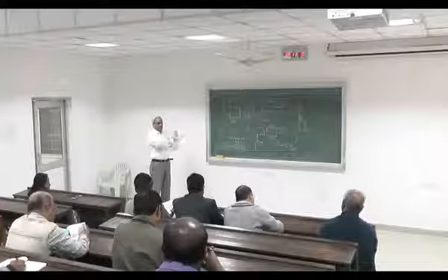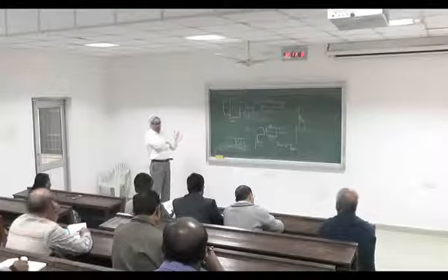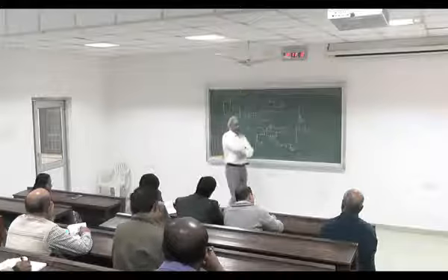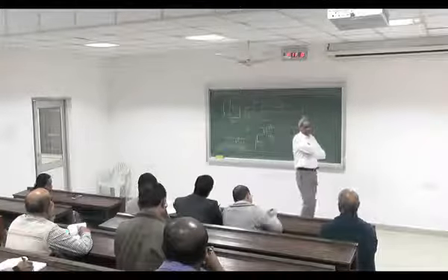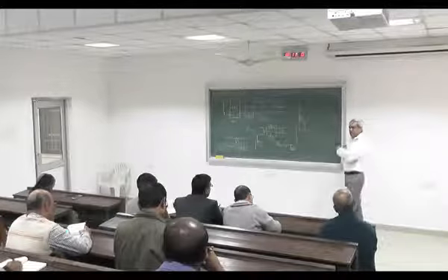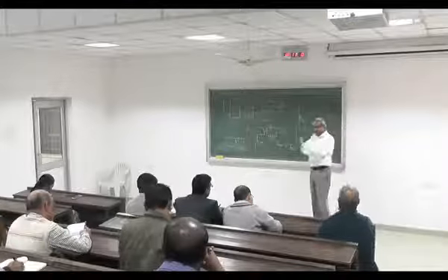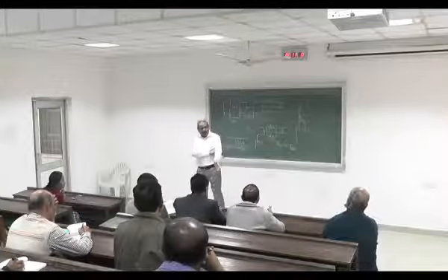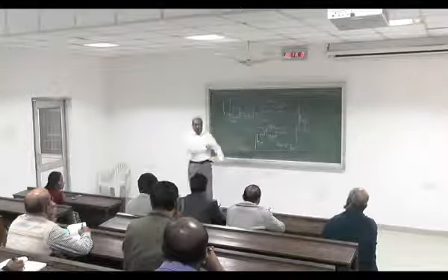While in case of resonant circuit, we basically have smooth transitions of voltage and currents, and some of these components become part of your resonant circuit. If you have a series parallel resonant circuit, then you can absorb the leakage inductance in the series and the capacitor in parallel.